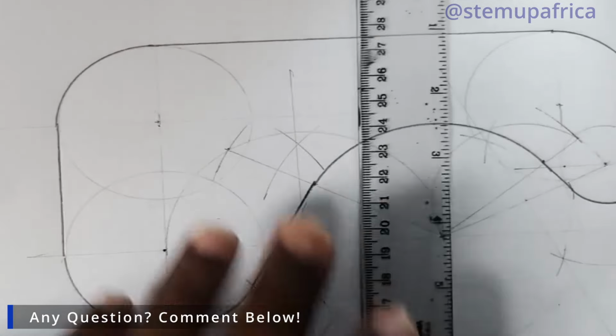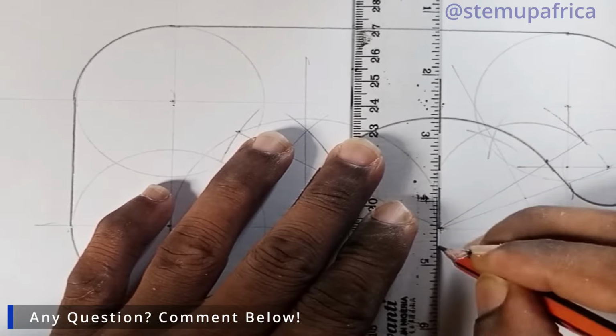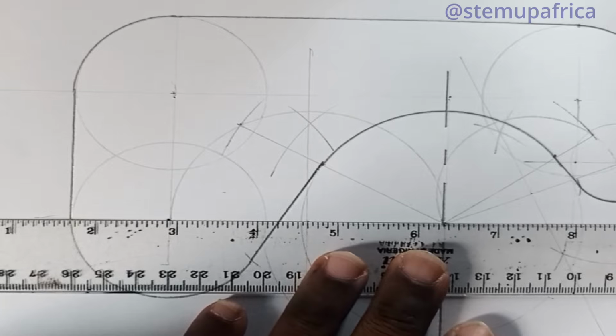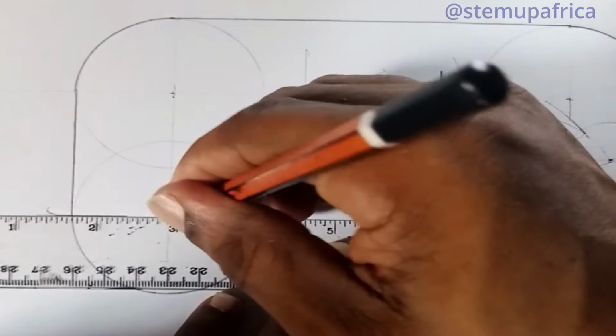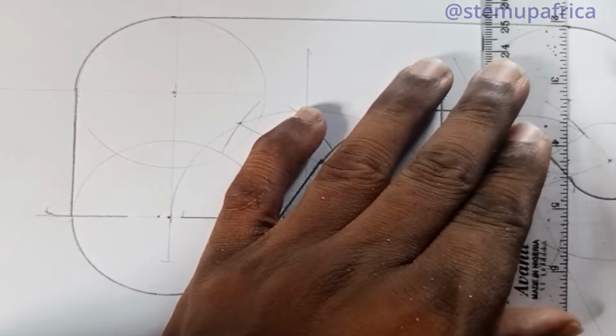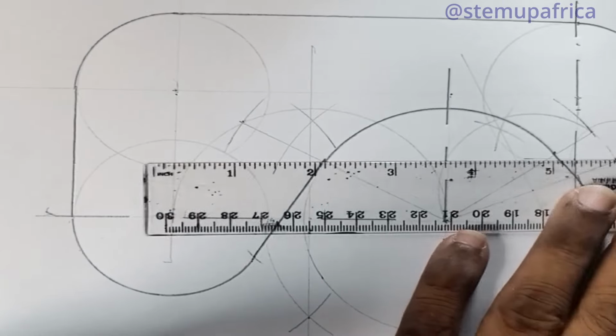All circles must have center lines. So I'll put a center line at this point. I'll put center lines. Make sure you don't forget that. Put a center line at this point. Center line here. Put a center line at this point.